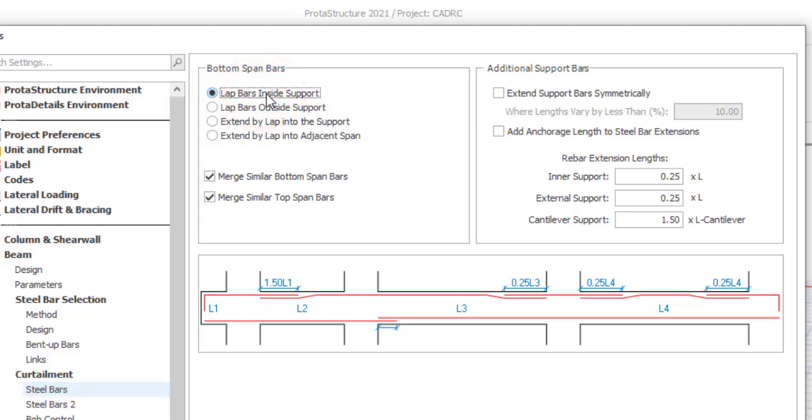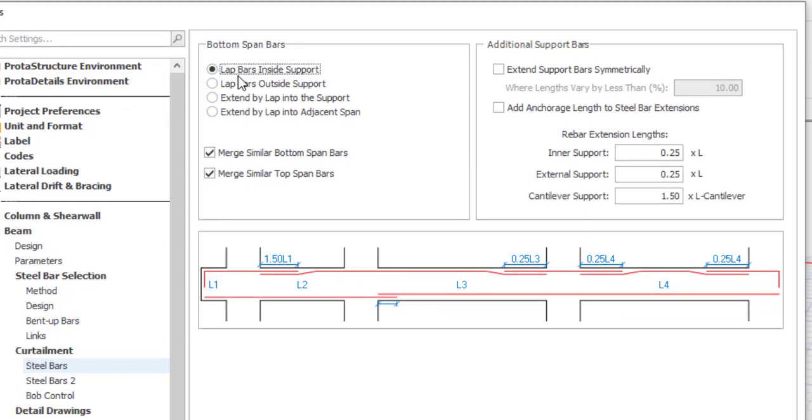you have your lapping inside the support, that is where you have the minimum shear force, because at your support your moment is maximum, but your shear force is minimum. Okay, so I will just lap it where I have the minimum shear force. So you can lap it inside your support, and if you don't lap inside the support, make sure you lap very near to the support. Okay, close to the support.